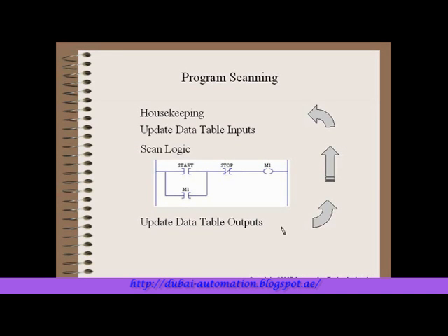Even though our PLC program is operating and driving relays and working with equipment in the field, such as a standard circuit you might normally deal with, you have to remember that it is a program and it has certain ways of operating. So if you're used to a standard program, it's going to be different, and if you're used to just working with relays, it's going to be a little different for you too.